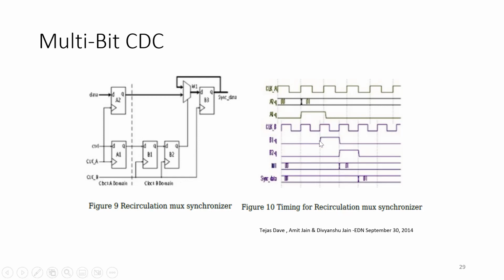Next, I have two D flip-flops in cascade, but those are working on another clock, the B clock. I have here this output high, but I didn't catch it. But here, I managed to catch it, and it went high. And this is fed to the next one.